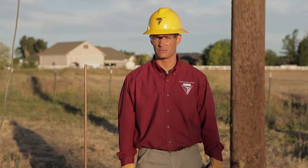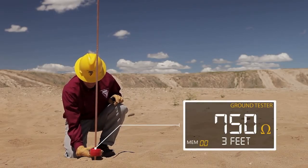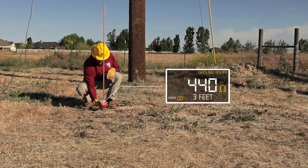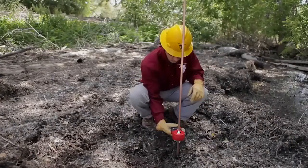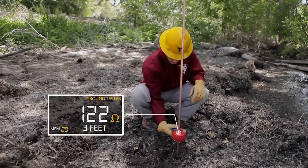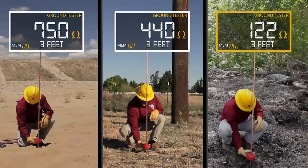Resistance is also affected by the type of soil the ground rod is driven into. I drove a ground rod 3 feet into sandy soil and got a resistance of 750 ohms, which is more than the ground rod driven 3 feet in the dirt that had a resistance of 440 ohms. I also tested the resistance in swampy soil at the same depth and got a resistance of 122 ohms. So of the 3 soils tested, the swampy soil had the best grounding source.